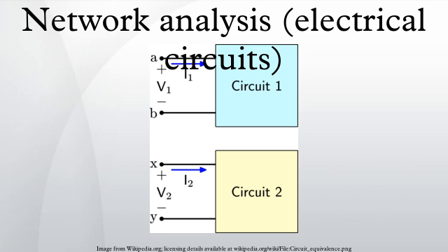Most commonly in electronics, transfer function is defined as the ratio of output voltage to input voltage and given the symbol A, or more commonly, A(jω), with the A standing for attenuation or amplification, depending on context. In general, this will be a complex function of jω, which can be derived from an analysis of the impedances in the network and their individual transfer functions.